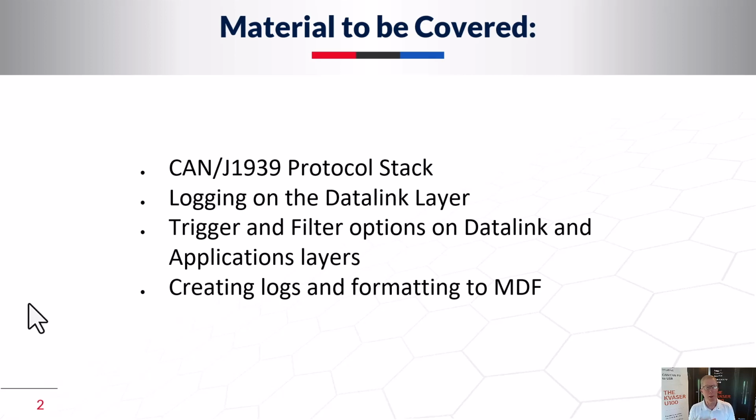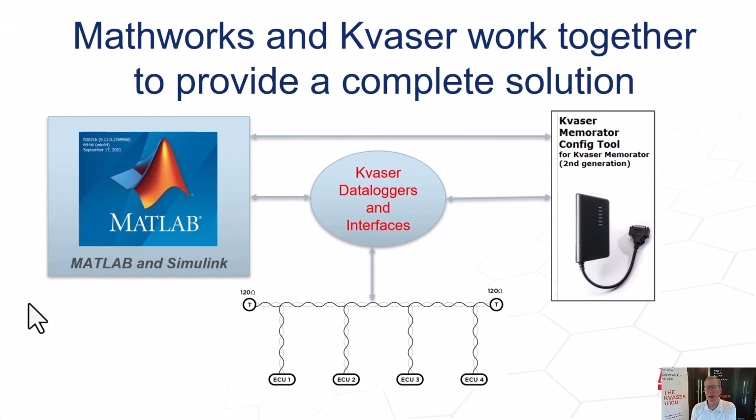I'm going to talk about the J1939 protocol stack for what we need to know to really understand the ins and outs of this data, logging the data on the data link layer as opposed to logging, filtering and triggering on applications signals in the applications layer, and creating log files and formatting to an MDF type of format for importing into the second half of this webinar, where MathWorks professionals, experts will show how to manipulate and work with this data on the MathWorks level.